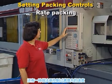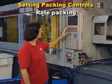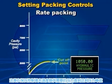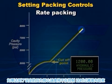Another method of controlling packing in the cavity is packing at a fixed rate by controlling the packing velocity. In this method, at the mold full point, the cavity is then packed at a constant rate. The control system maintains a set packing rate by using whatever injection pressure is needed, up to the maximum injection pressure setting. If the maximum injection pressure is reached, however, there will be a loss of control since process adjustability is no longer available. Packing is ended when a preset cavity pressure is reached.